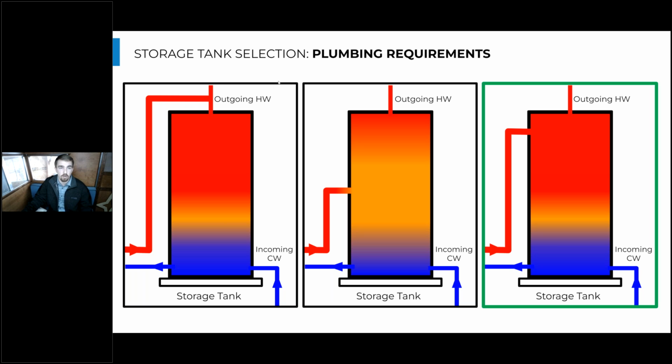Any variations in your heat pump leaving water temperature, which will vary slightly as the heat pump warms up and as things change, are seen directly by the mixing valve, and the mixing valve has to respond to that really quickly.